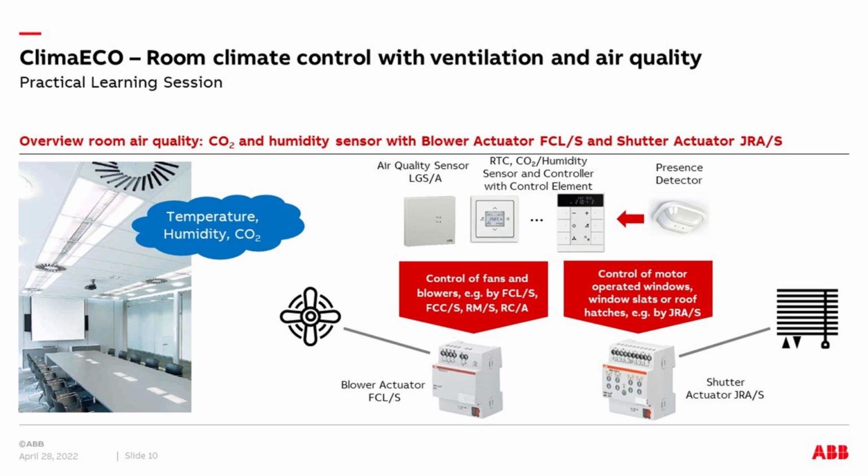So it's possible to integrate more components, even an analog actuator instead of stepwise control. I come to this in the next slide. You can say, okay, I would like to have the continuous control of a fan via a 0 to 10 volt signal, for example. Then also an analog actuator could be involved.